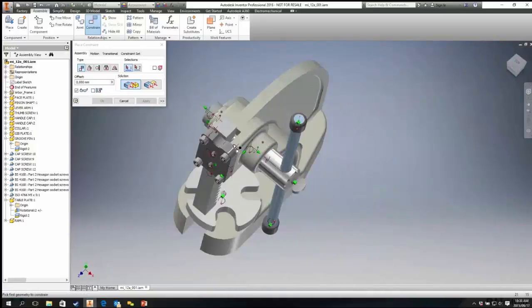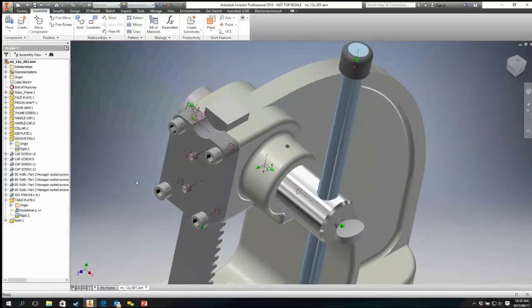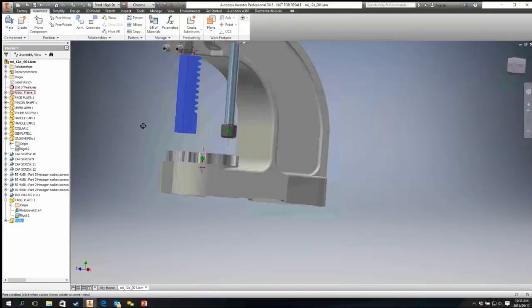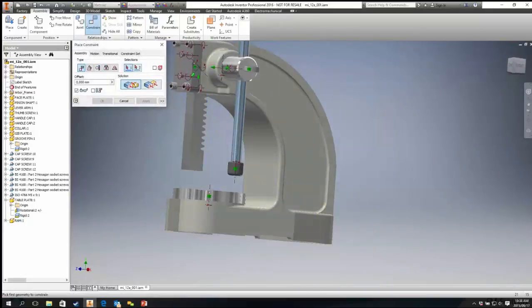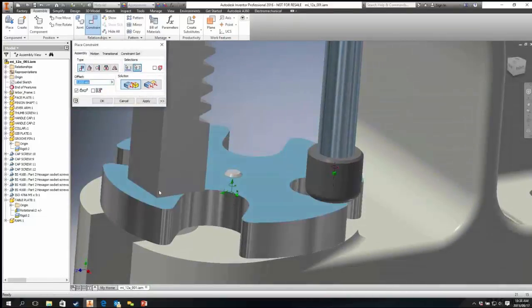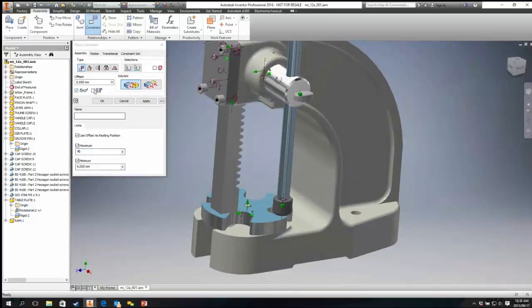Okay, but what I want to do now is I'm going to quickly position this on the side over here, so that I can show you how we can constrain this position down here at the bottom so that a node can only move a specific distance. And once again, with the normal mate constraints, if I mate this position to the base, I can look at this extended option to say I want to use specific limits. The offset value is sitting at 0, so let's use that as our resting position. So the minimum position that I can move is 0, but let's maximize this value to say 40 millimeters. Which means if I look at 40, just as an example, where it's sitting, it moves up to there.